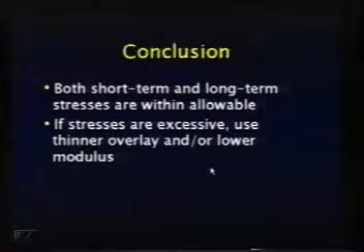If the stresses were excessive, then the thing to do would probably be to use either a thinner overlay and/or a lower modulus. And generally I would want to use a lower modulus than the one we used. We simply were using an example of some polymer concretes that we had tested in the laboratory.